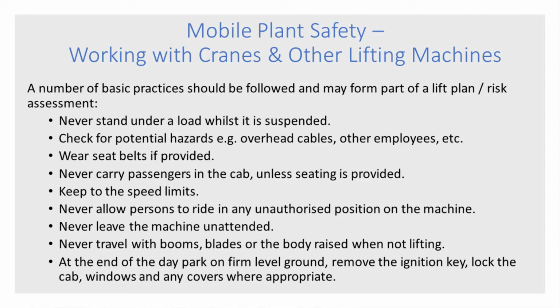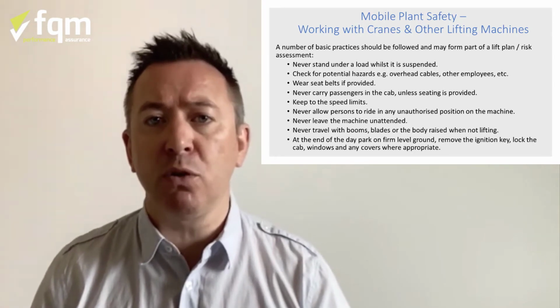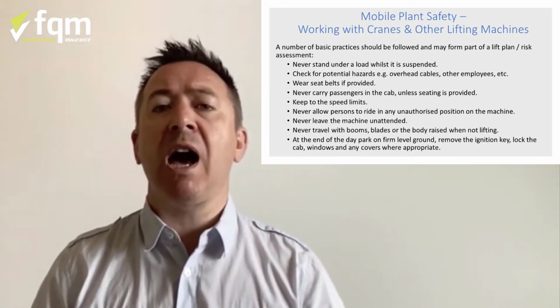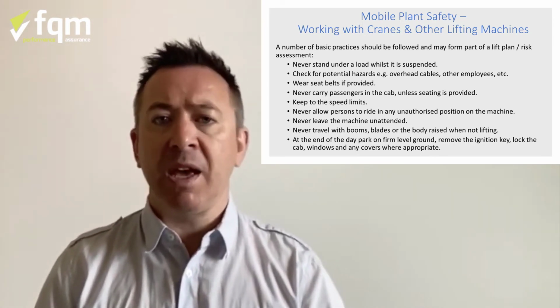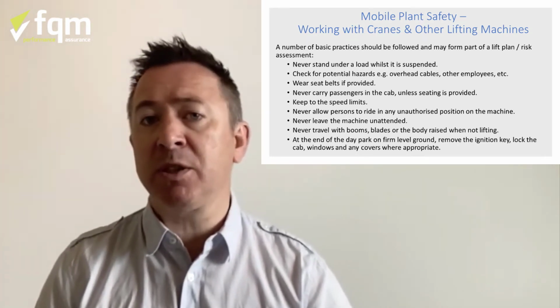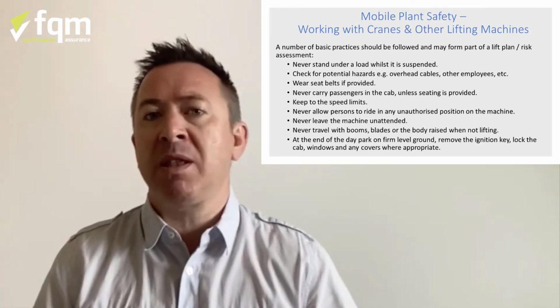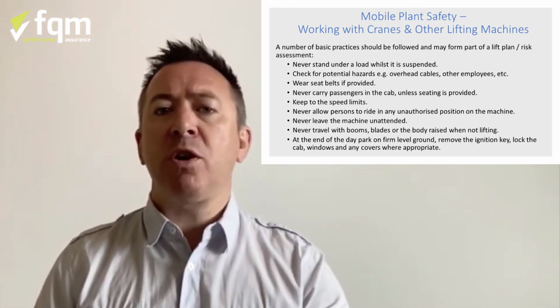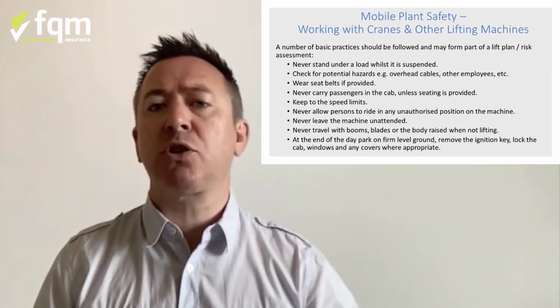A lifting plan can follow two ways. One can be generic, associated to a standard lift, which looks similar all of the time, and the other can be dynamic, much more related to a critical lift that will take place that's not a normal activity. In both cases, they should guide you through steps that you should follow in order for you to control the hazards and reduce the risks associated to the activity. Again, it's often that we need to use banksmen or slingers to support us in this, and there are a number of human errors that can occur associated to that. One of those key ones is around communication and who takes control, often the main operator. So please be aware of some of the rules on your site associated to lifting kit and some of the requirements that you need to follow.